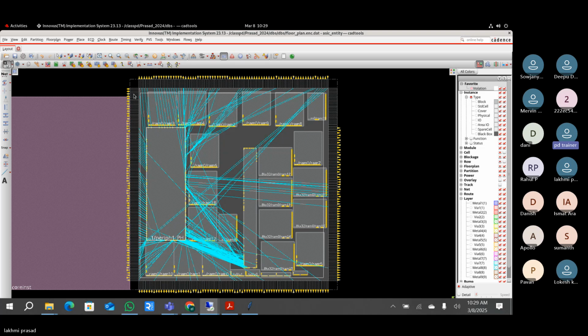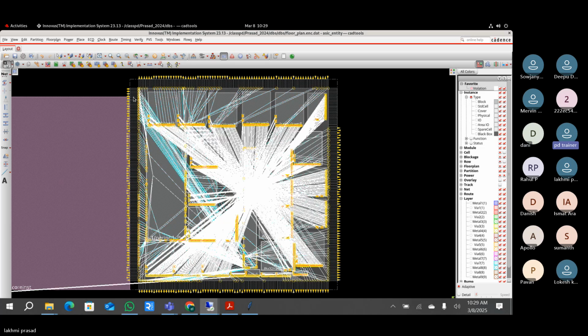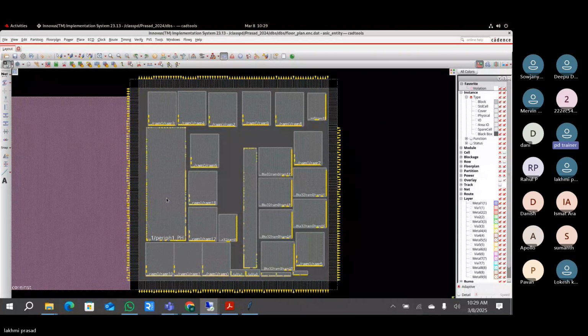No, don't select all the macros together. We are going to align macros row wise and column wise. So don't select them together. Okay, then what do I have to select first? Select the macros at the top row alone. This alone. Yeah, only the macros at the top. Including the small one, Christina? Yeah. Okay.